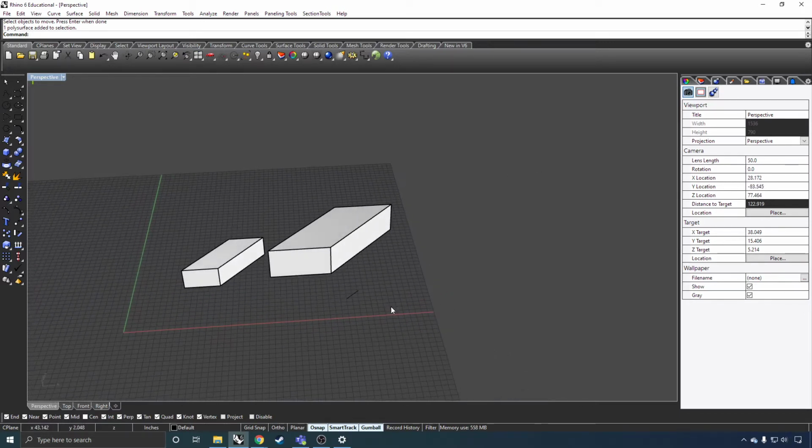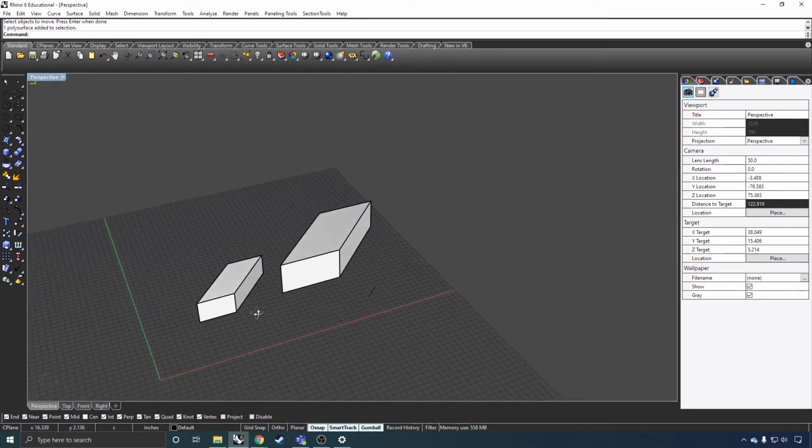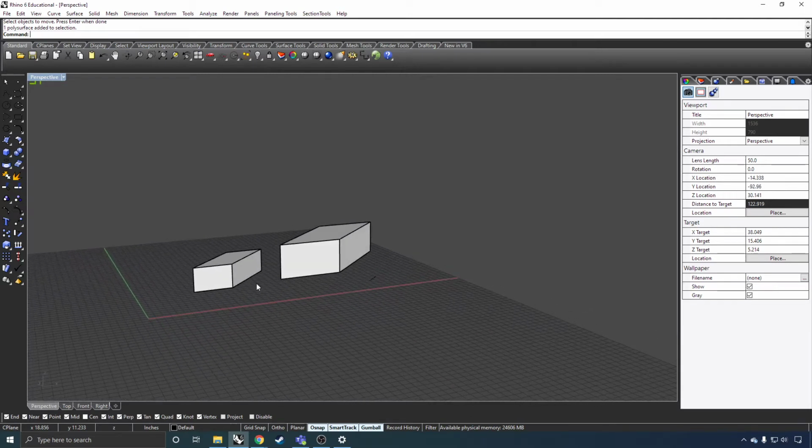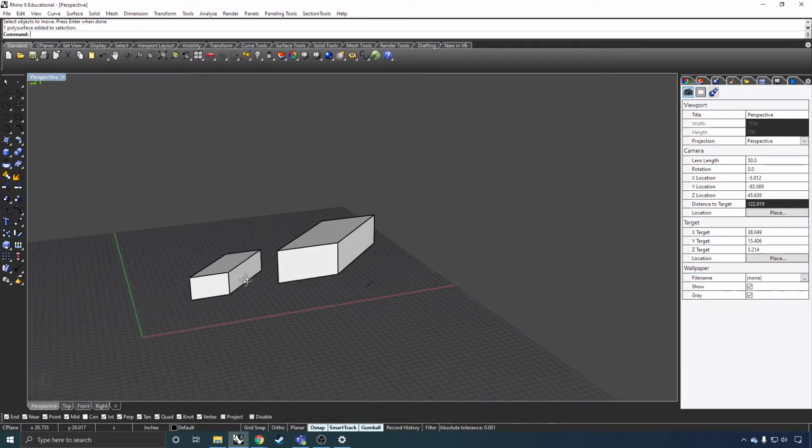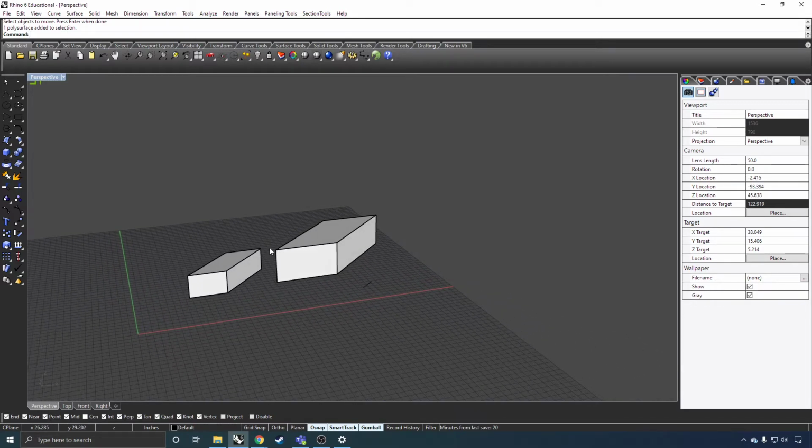So in order to start talking about the tools, we're going to have to talk a little bit about how Rhino makes and classifies geometry. So most modelers, or at least traditionally most modelers, have been polygonal in nature. So they will make a shape out of many or as few triangles as possible, depending on how you've defined your shape, in order to approximate a 3D form. Rhino doesn't do this as its default. It can. So meshes are what those things are, and there's a whole set of mesh tools up here.